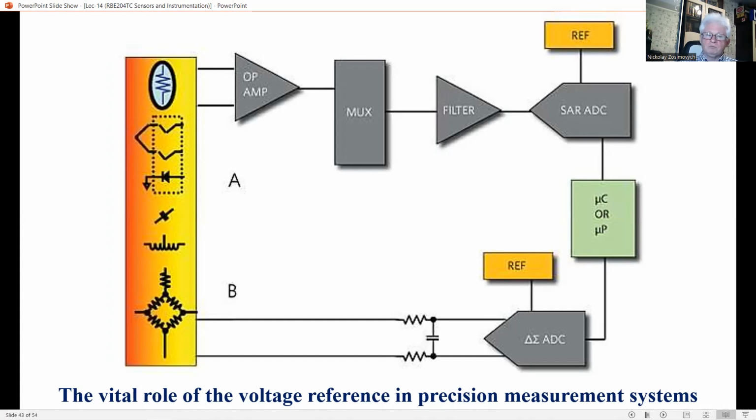Often, the digital output from the controller has to be converted into analog form for this reason. Both analog to digital conversion, ADC, and digital to analog conversion, DAC, can be interpreted as signal conditioning or modification procedures. If more than one output signal is measured, each signal will have to be conditioned and processed separately. Ideally, this will require separate conditioning and processing hardware for each signal channel.